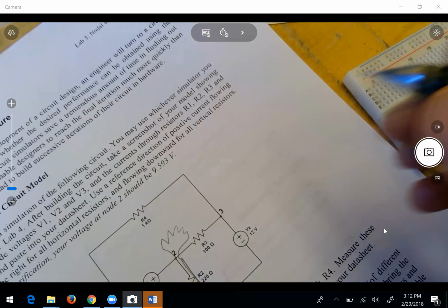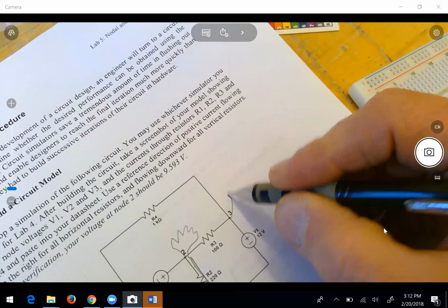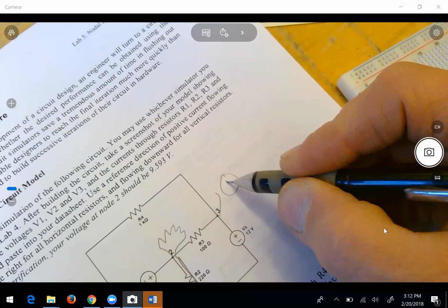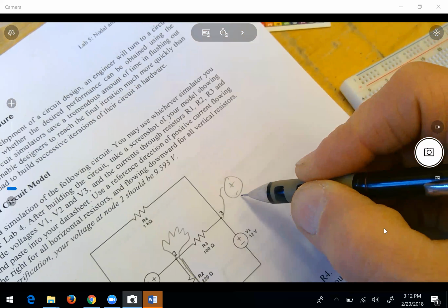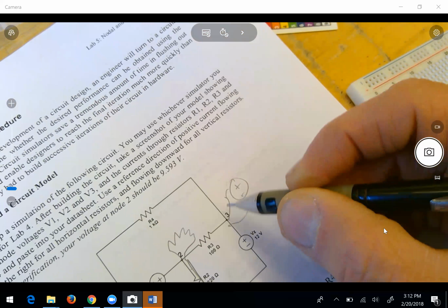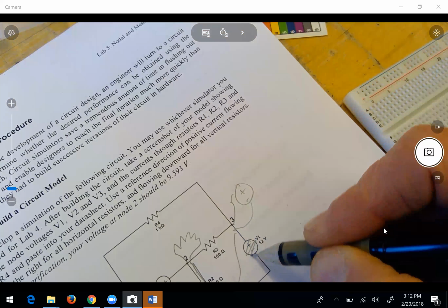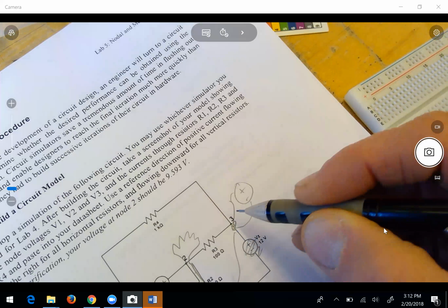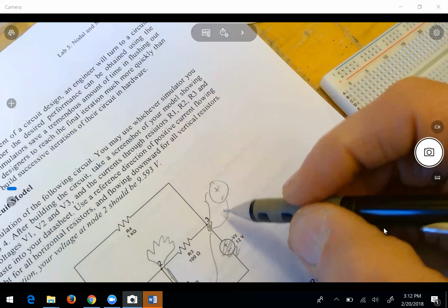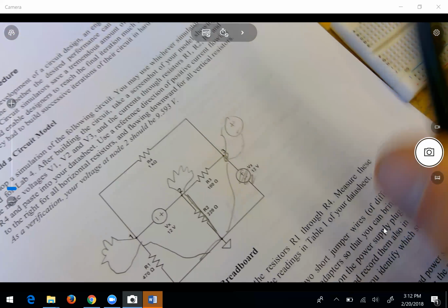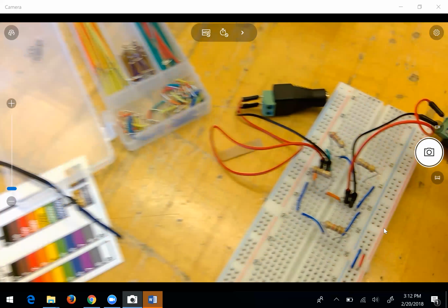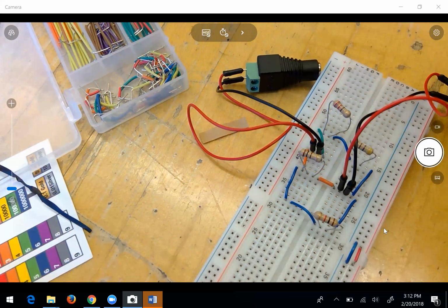And your voltage source is also being shorted out. You're sort of applying 12 volts across ground and ground. So you're going to short out your voltage source because you've basically attached the plus and the minus leads together. See what I'm saying? You're doing that to all your resistors, so those need to be reconfigured.